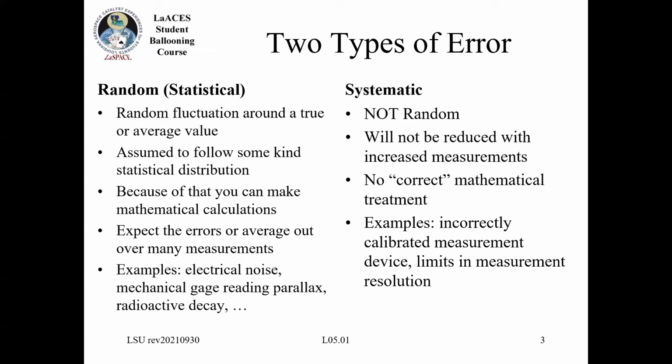So if I'm measuring the length of something with a ruler that's marked off in millimeters, I would assume that it has a minimum resolution of like 1 millimeter, maybe half a millimeter. And that uncertainty is not going to get smaller. I can't average that out because it's the limit of the actual tool you're using to measure.